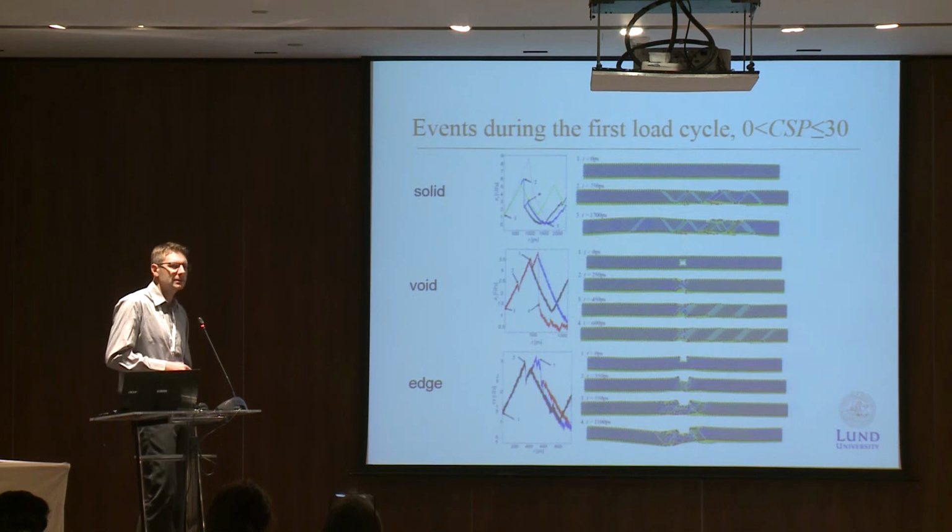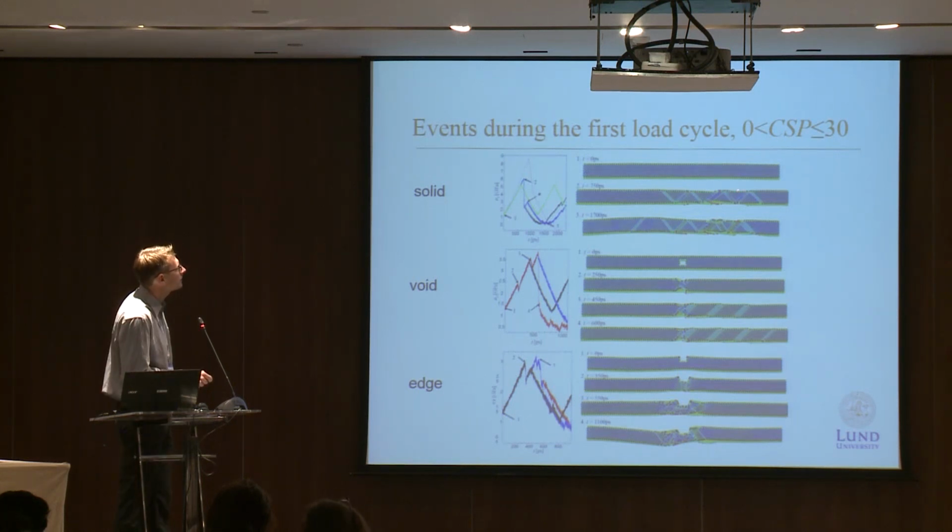And this is when plasticity forms. So we have activation of a number of slip planes here in close-packed directions that we can see. And this continues until we reach maximum load, and then we start to push the beam together again, and we can see that the beam has been bent slightly.